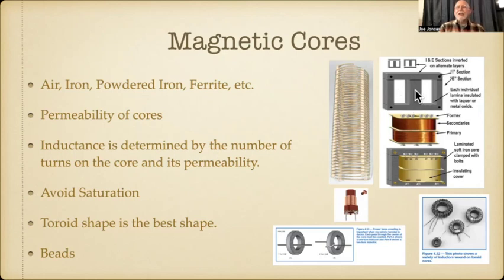But Scott, you've done that though, have you not? Oh, you bet. Yeah, you can take a transformer like this, tear it apart, pull this part out here, keep the primary, and then change the secondary. You can change the voltages and do all kinds of things.